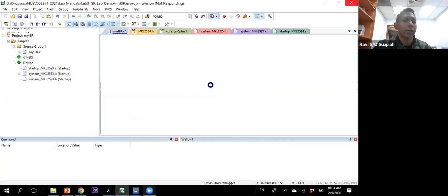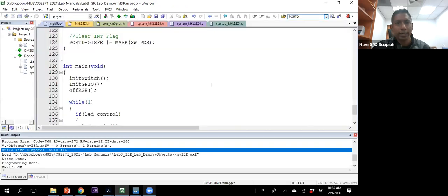For those of you coming to the DSA lab this Friday or anytime next week, you can hook up the oscilloscope. You can connect the switch to the breadboard, and then from the breadboard to port D pin 6, or directly clip it to the switch, and observe the debouncing.